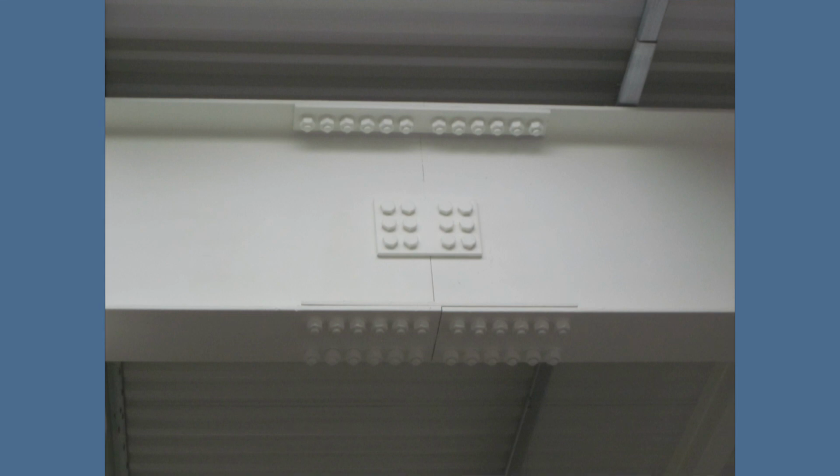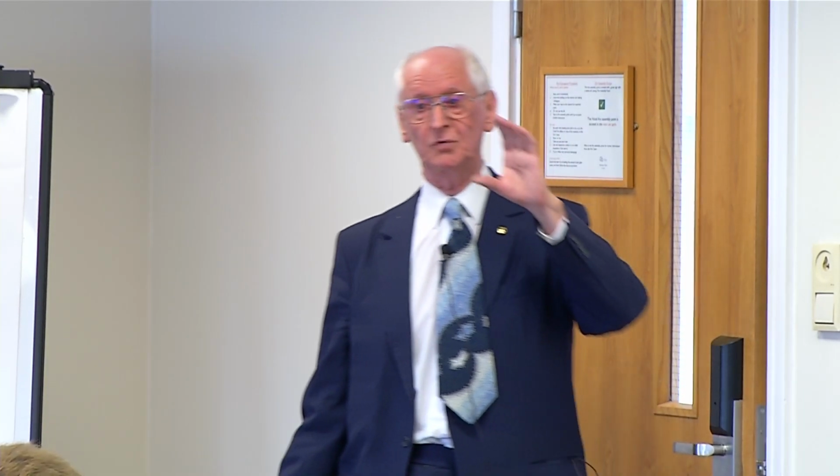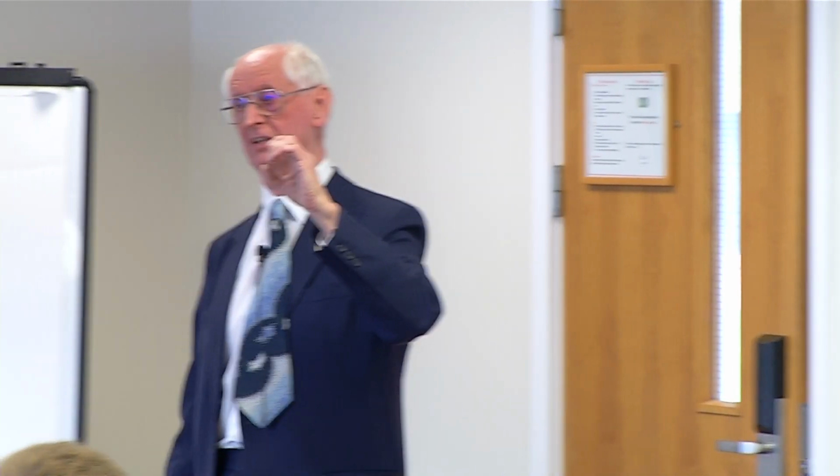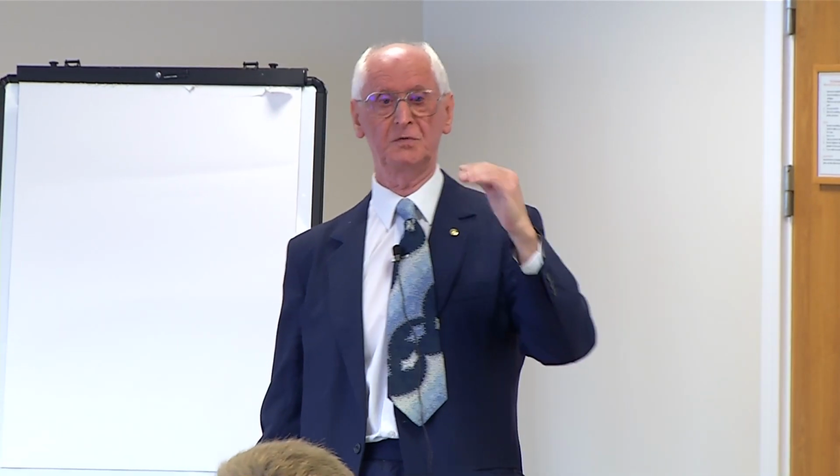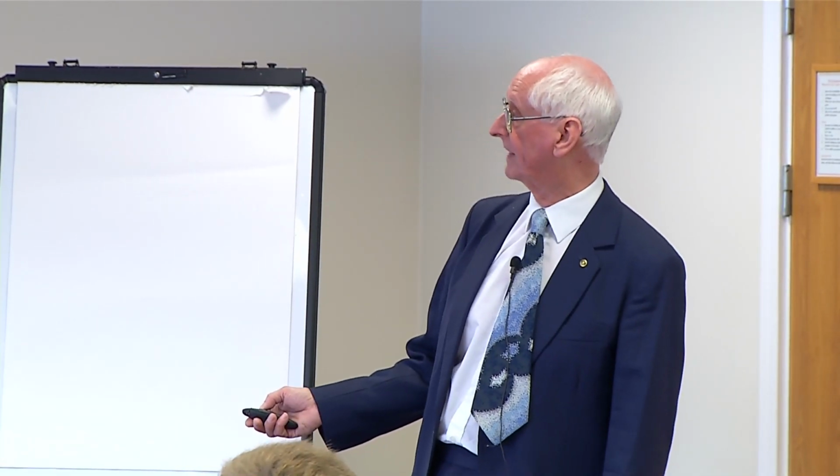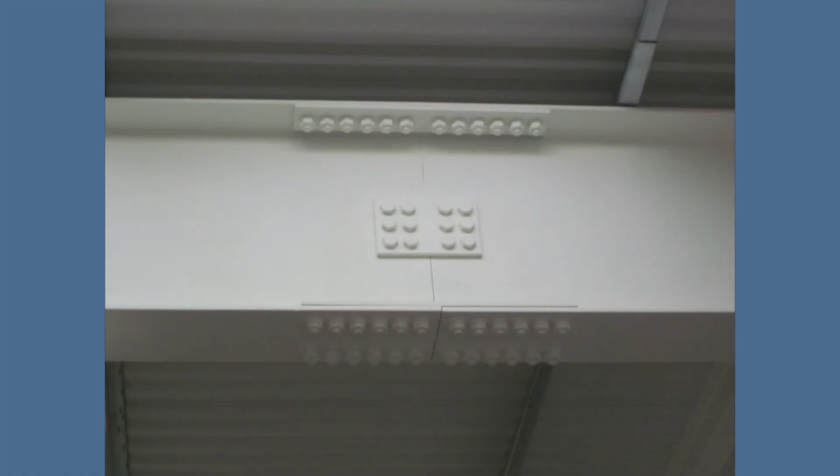But if you come back to proper sections, the other problem is lack of geometrical fit. And here you can see a really deep section, that's about 600 mil deep, and it's a very strong structural connection, but here, the bottom flange doesn't touch the plate. Now, these connections rely on friction, and the bolt being clamped up tight provides the friction between the plates to transfer the force. So here, that's not happening. And these 12 bolts now are all acting in shear to try and transfer the force from that side to that side.